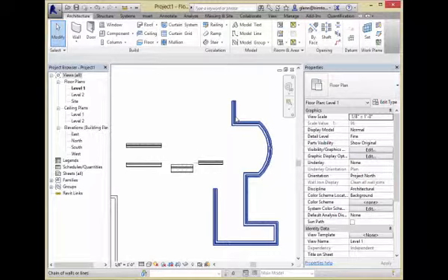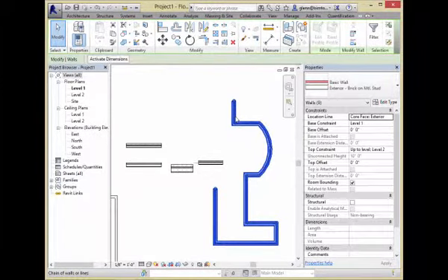Maybe you wanted a chain of walls. Okay, and when that's highlighted in blue, you can then hit once with a mouse and grab them all. So that notion of tapping the tab key to rotate things, you're going to use it a lot. People kind of keep on coming in as one of those little shortcuts you use an awful lot. So you can try that if you want.